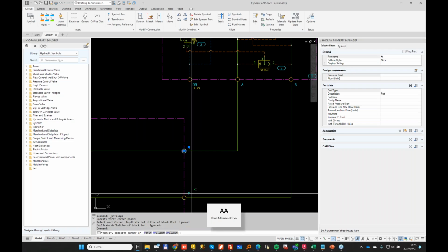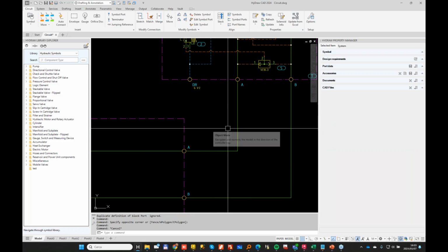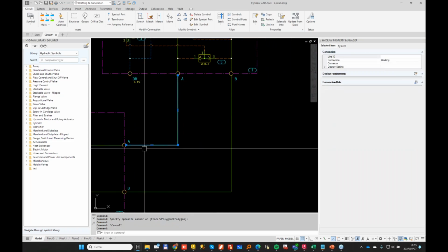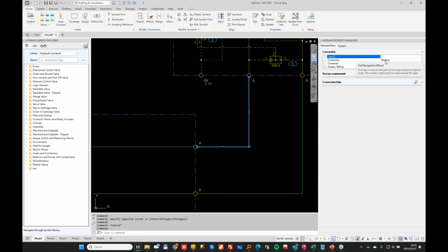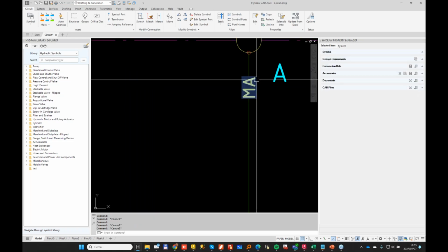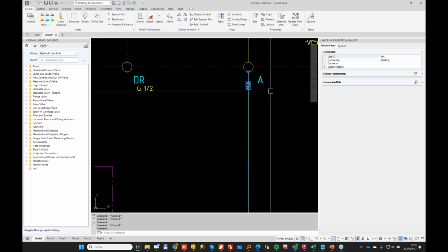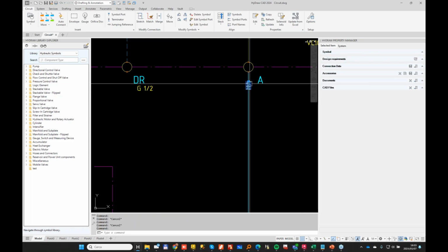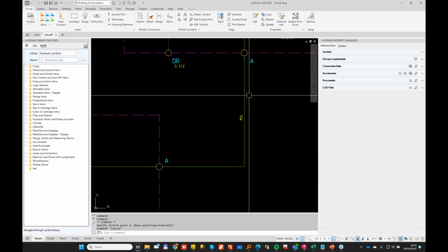And as of now, I'm not going to size the port. I start from the connection line. So basically, this line is where I'm starting my work today. And let me give a name to this line, MA. So when you provide a name to a line, the name will automatically be displayed on top of the connection line. It is possible to move the text where you want along the connection line.